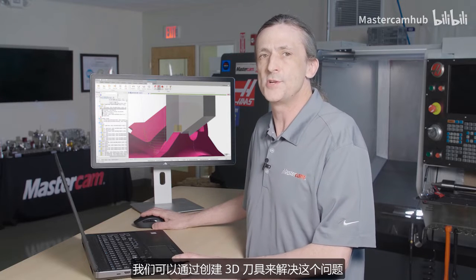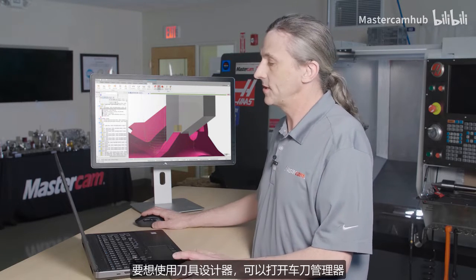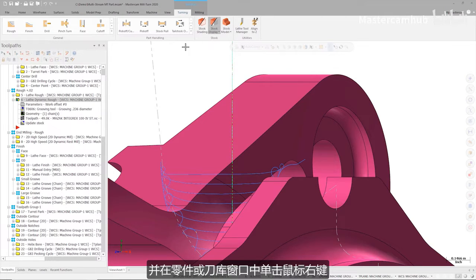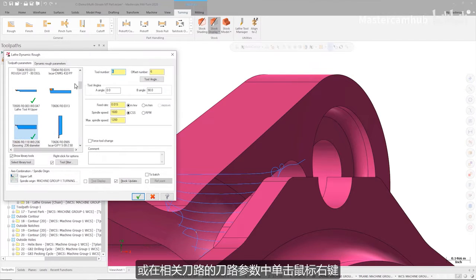What we can do to fix this issue is create a 3D tool. I can launch the tool designer by going into the lathe tool manager and right-clicking in the part or library windows, or by opening the parameters for my tool path and right-clicking in the tool display window.